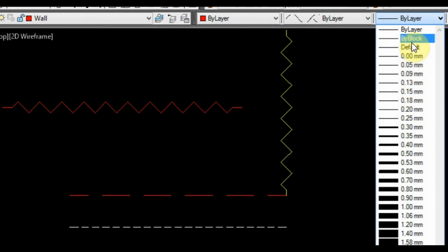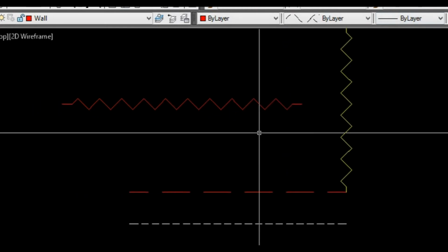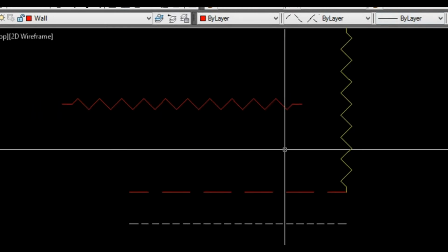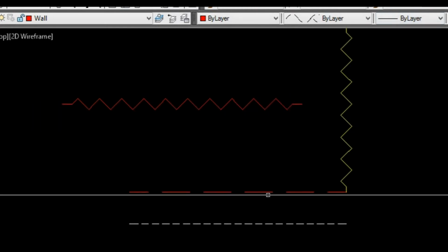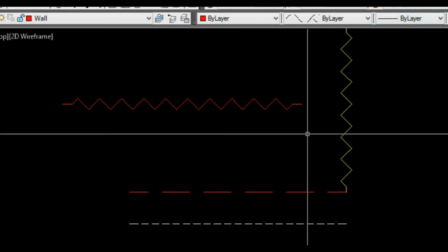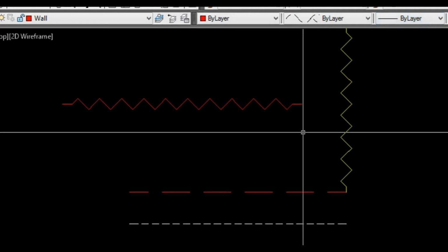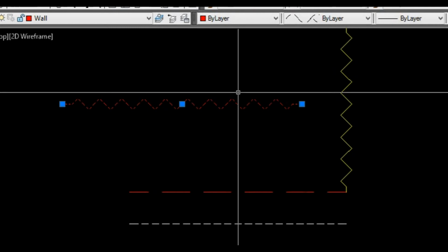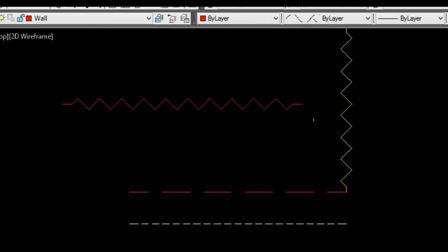The reason being is, for instance, I could have many lines on a layer and they could all be red, but they could all be assigned to different line thicknesses, and I wouldn't have any idea what the different ones were until I either went to plot and found quite big differences, or if I individually selected each one to find out what it is.